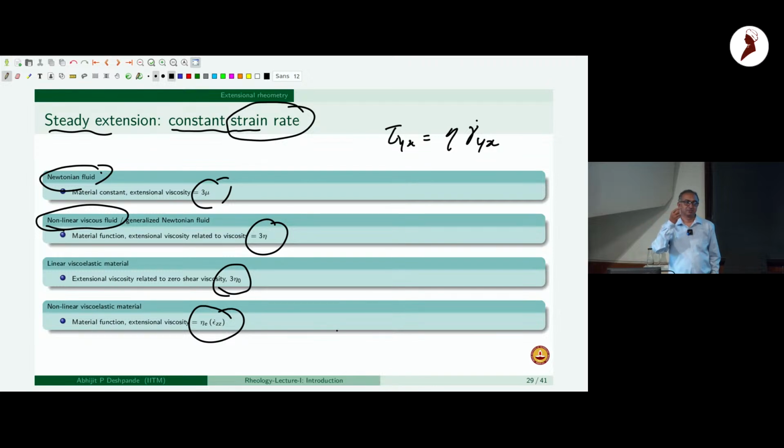The prominent example of this is branched polymer versus linear polymer. Both of them show zero shear viscosity and shear thinning, but the branched polymer, because of the way the entanglements are not able to relax in extensional flow, gives you a lot better stretching. So you can achieve much faster rates of spinning and get much thinner fibers reliably.